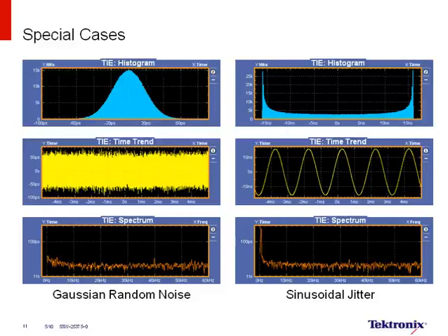On the bottom left is yet another view. This is commonly referred to as the jitter spectrum. In this case, again, the vertical axis is jitter, but the horizontal axis is frequency. So again, when you have a Gaussian or random noise, it's spread out evenly across the entire spectrum. On the bottom right, you see the jitter spectrum when you have a strong modulation profile.